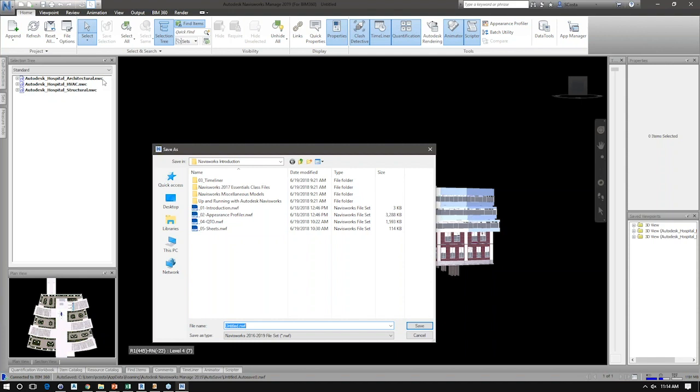Navisworks needs to create an optimized version of that file in order for it to display on the screen. So that optimized version is the NWC format. The nice thing about the NWC format is that it's linked to the original authored file. So if I make changes to those files and I update the NWC file, my federated model will also be updated, since at the end of the day, what I'm going to create after appending several NWC files is an NWF file.